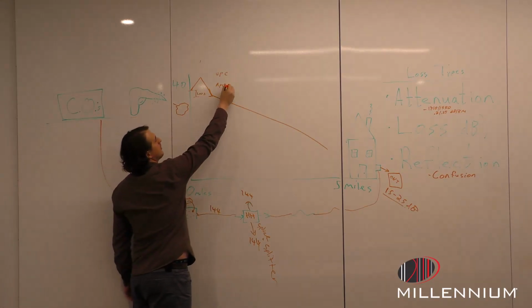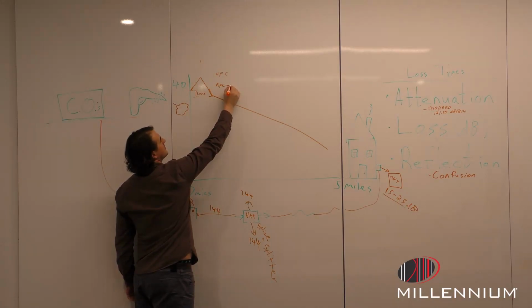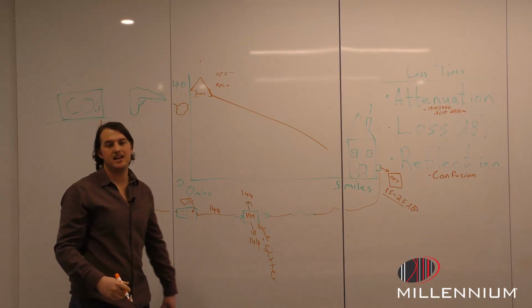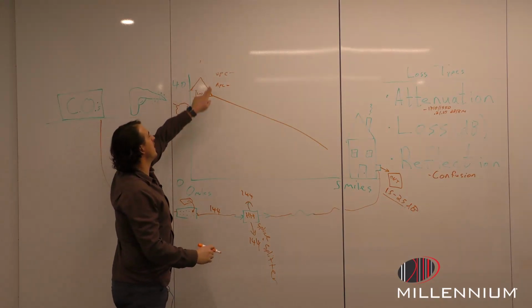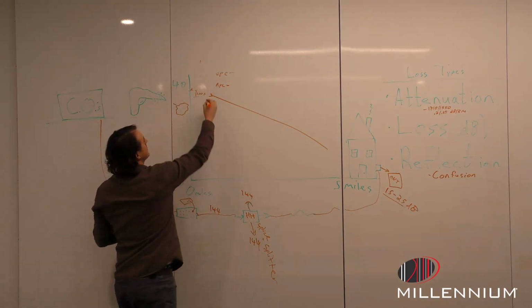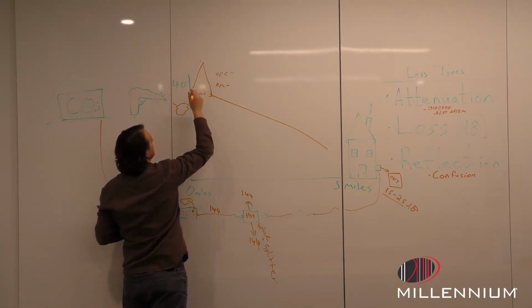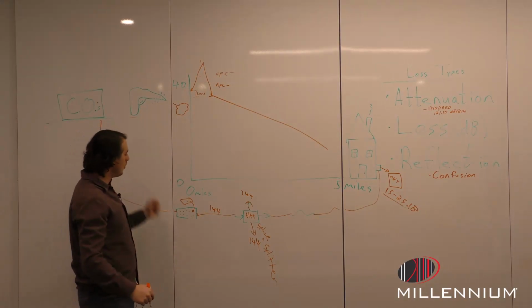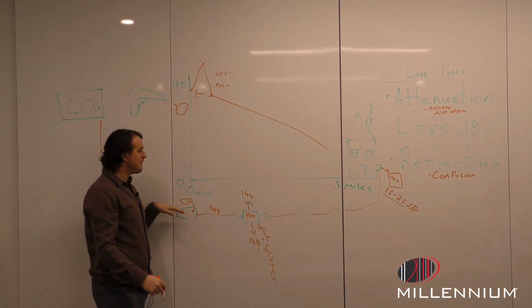And talking about connectors, the loss associated with the APC connector or UPC connector, they're going to be about the same. It's just this reflective event that is going to change. So a UPC connector has a lot of reflection associated with it. All right, cool. So we just went through our patch panel.